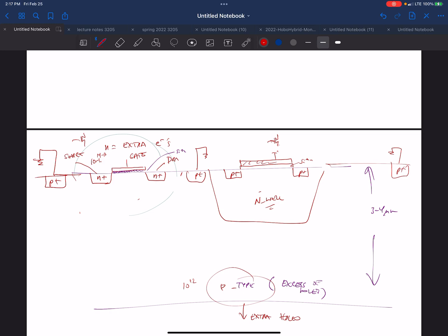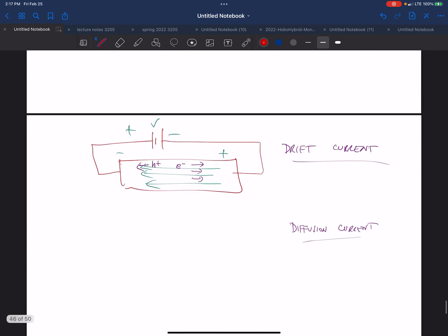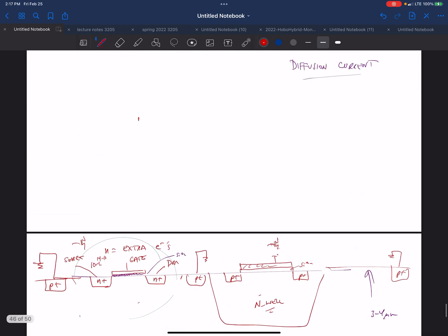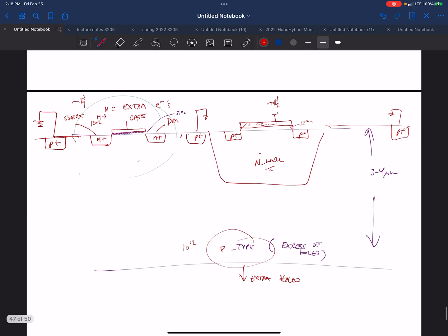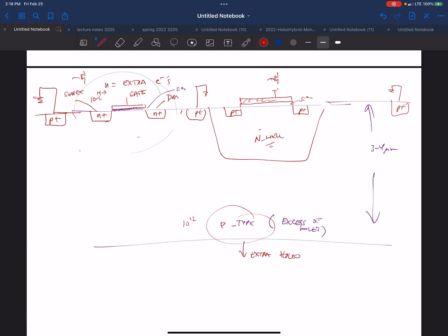Okay? This means that if I have N transistors, all their substrates are grounded. Okay? I cannot have a situation where I have another N-type transistor and hook up its substrate to something else. It's just not something I can build in this process. You know what I'm saying? If I took this P plus and connected it to plus 5 volts, I would get a short between plus 5 volts and this ground. I cannot do that, right? They've got to be all shorted together and all grounded.